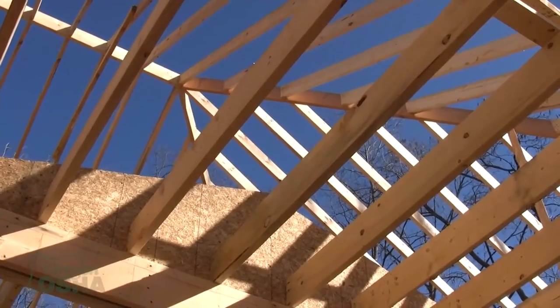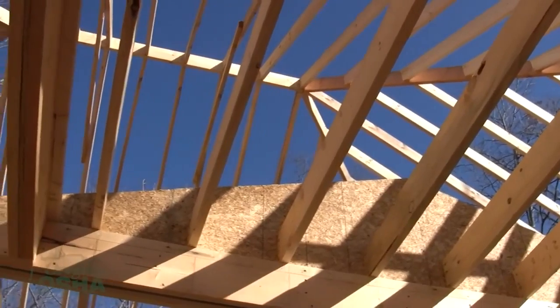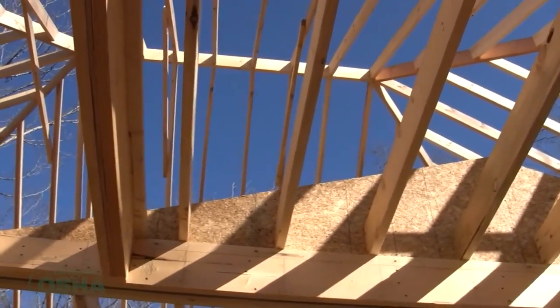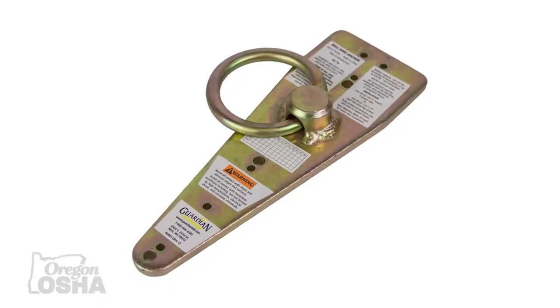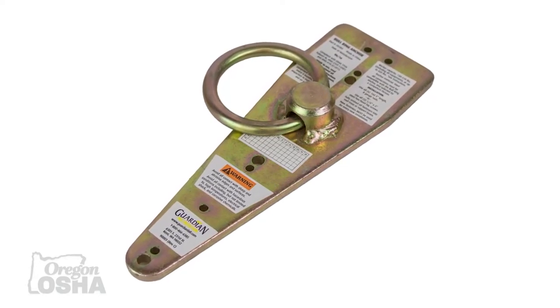One common thing we'll see that obviously isn't approved is people wrapping their rope around the peak of the truss, around the rafters. I get that it may handle that weight, but it's not rated for that, and you don't truly know if it will. There's also a leave-in anchor that can be used for the attic, which you basically nail to the side of the peak of the trusses. This provides an anchor point if you're going to be working in the attic or, say, above a stairwell.